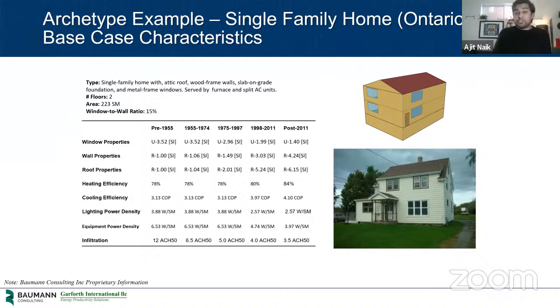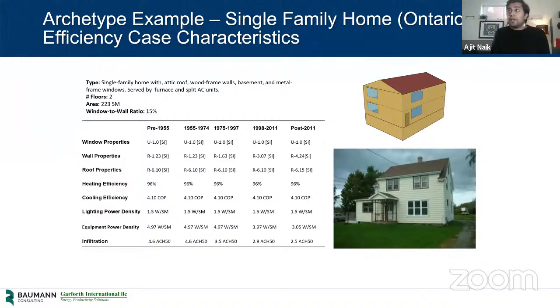When we developed these models in Ontario originally for some cities in the suburbs of Toronto, we moved on to a project in the city of Windsor, which has a much older housing stock. The city sustainability staff had actually performed a ton of blower-door testing. When our models came out showing way too little heating energy, we connected with them and reviewed the blower-door studies they had done on a few hundred homes, and we realized that the infiltration rates in Windsor were significantly higher. By going through an iterative process, always working with our teaming partners, we were able to come up with a reasonable set of inputs that defined the building stock as it was, and we got a very good match to meter. Could you advance the slide, Peter?